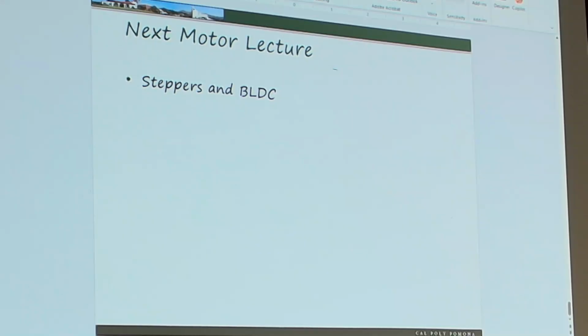So omega dot is a big number. Omega is a big number, right? Power is a big number, right? Current, if voltage is held constant, becomes a big number, right? Power is power out. Which means if my current is insufficient, or if I want to move very quickly, my current isn't there to do it, I can't move very fast.